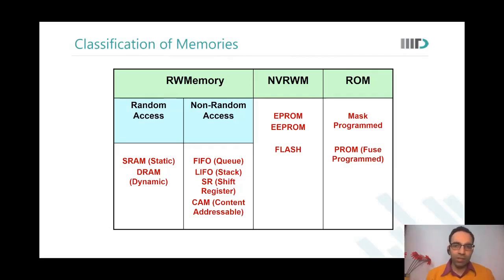So is this point clear to everyone? When we are saying mask programmable or mask programmed, it means that at the time of designing the mask for that particular chip, I already decide what is the data that needs to be stored. So can you ever change the content of a mask programmed ROM? No, sir. No. But because it is mask programmed, we are already preempting what data needs to be written into the ROM there. It is much, much denser than EPROMs and EEPROMs.